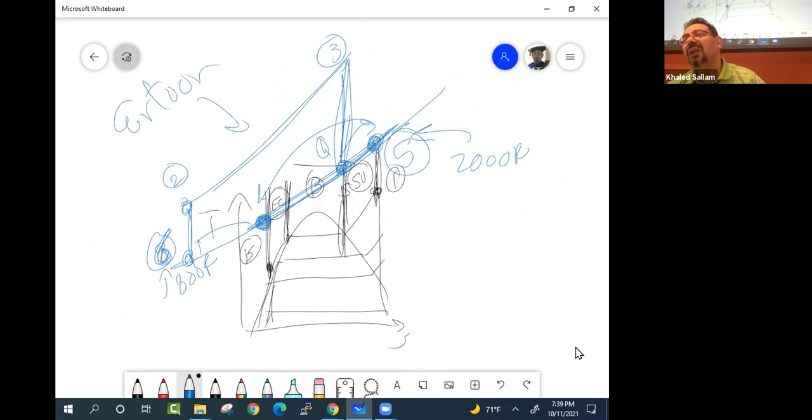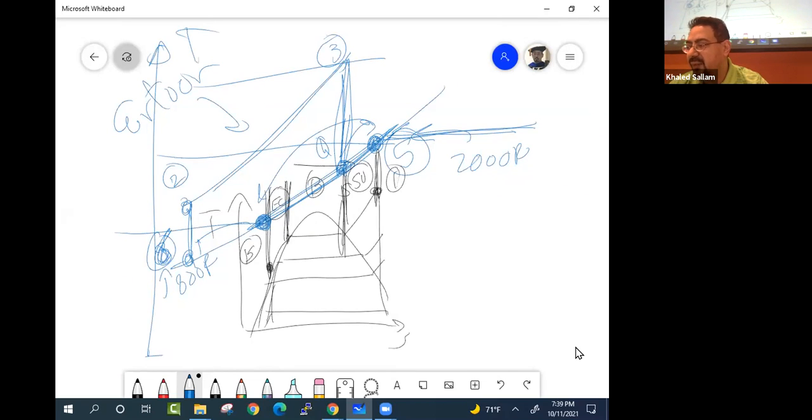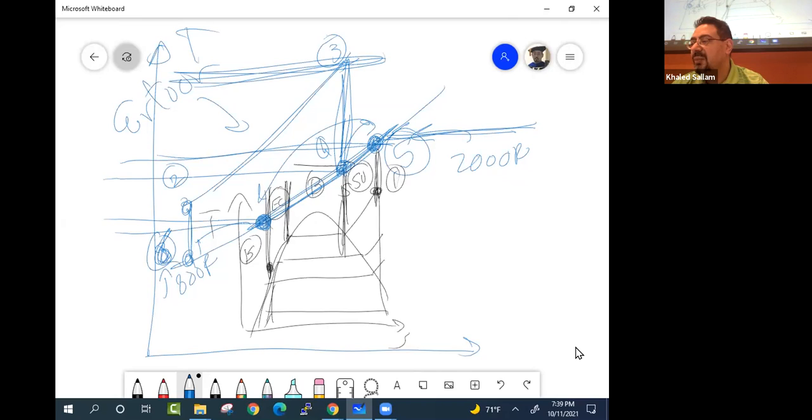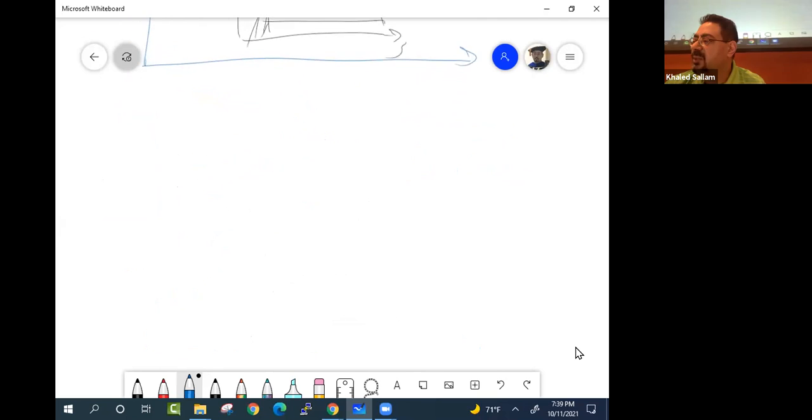I mean, you can use the temperature scale on the TS diagram, but just realize that you should use, of course, the scale of the T, right? So this should really sit at the right temperature, and this should read the right temperature, and the right temperature. But you just need to realize that you don't read the H, for example. Don't read the H or the entropy or anything. Got it? You're just plotting the Brayton cycle on top of the Rankine cycle, so let's make a cleaner sketch.